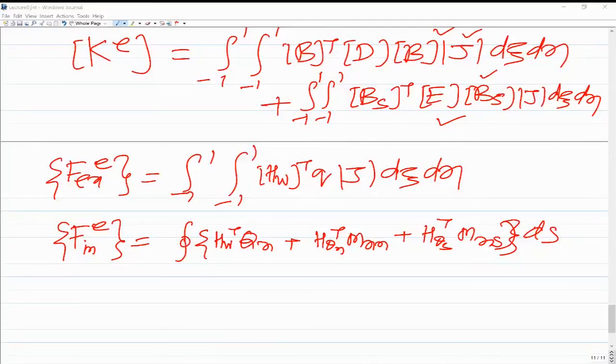But there, del w by del x and del w by del y are derivatives of w. So corresponding to w itself there are 12 degrees of freedom when we talk of only 3 degrees of freedom at each node. Here, in first order shear deformable plate theory, corresponding to w there are only 4 degrees of freedom in the element, w1, w2, w3 and w4.